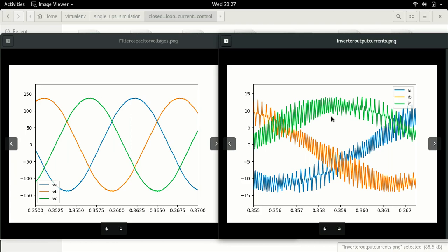But that is the entire concept of a higher order filter. Remember I said the inductor itself forms a filter. It's an energy storage element. The capacitor itself forms a filter. It's an energy storage element. These two together form a second order filter. So the inductor filters the current but is only able to filter it to a certain extent. The capacitor further filters it and produces a smooth output voltage. This is what is happening. You have a two-stage process, and this is why we are even doing a two-stage process. We are first controlling the current and then controlling the voltage.